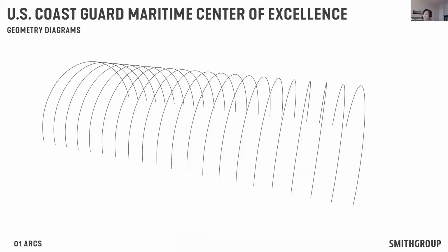on simple geometries. So using the Grasshopper script, we first set out a series of simple arcs as seen on this image. We then created points on these arcs using sine curves. Sine curves can be found in nature like ocean waves, and they were appropriate for the design concept for this project.